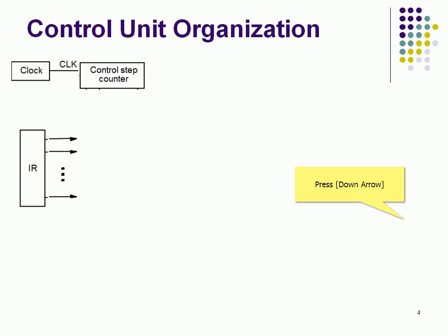So it is a step decoder. It will try to release separate timing line signals, so that each signal will be augmented with the timing signals. The step counter is going to release the timing signals, which help us generate separate signals for every instruction, right? So for every instruction, there is a set of timings going to be released here.